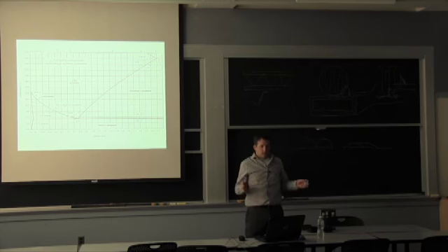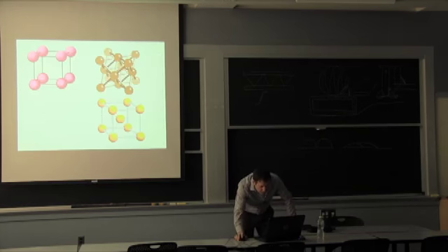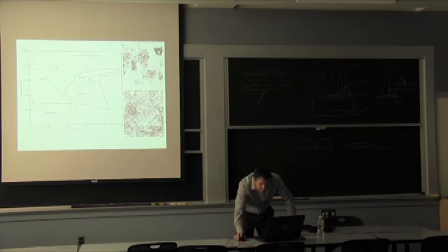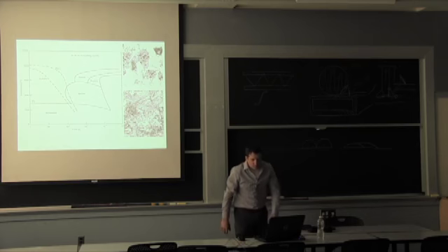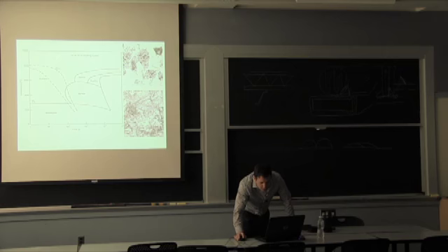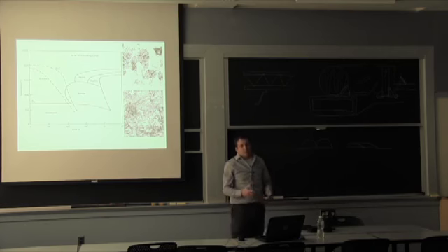Now, as soon as you start cooling faster, and I believe I got a graph of this, when I say cementite, that's this zone here that's got black and white. The faster you cool, the smaller would be the spacing between the different cementite layers, the different black layers. And that's what gives you strength.